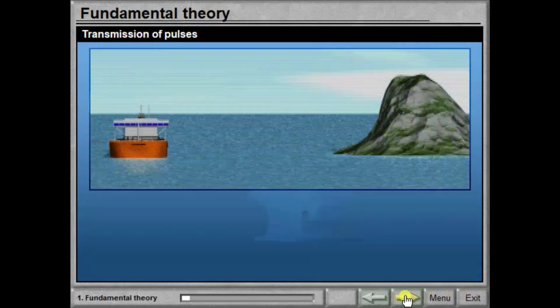In the radar, a short burst of electromagnetic energy is transmitted, hits an object, and then returns. Since the velocity of propagation is known, it's easy to calculate the distance to the object, as long as we are able to measure the time from which transmission is started until the echo returns. The transmitted pulse must be short in order to distinguish between echoes located close to each other.